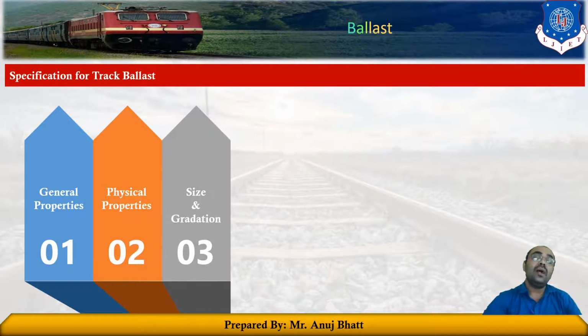While talking about the major coarse aggregate, the maximum size of aggregate that we use is about 65 size, and the percentage of such coarser aggregate should be at most 5%. Also, the 40 size of aggregate should be used as 40 to 60% of the total volume.